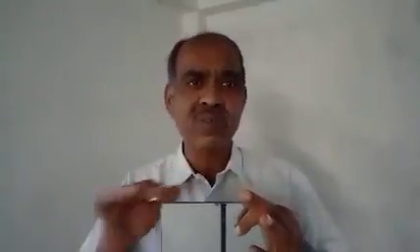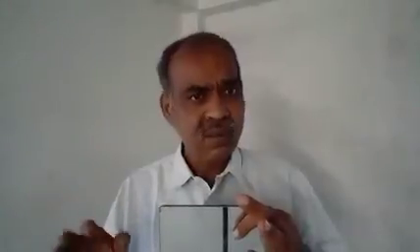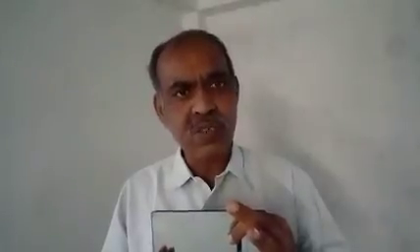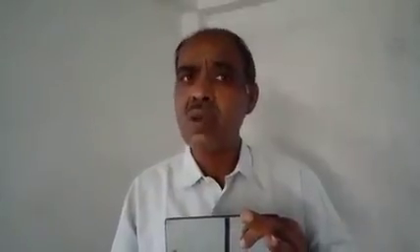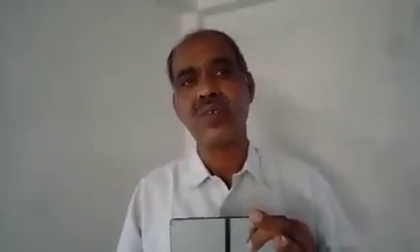The first term vanishes automatically, RA into 0 was there. In the second and third term, L is present. In the right hand side, 0 is there, so divide both sides by L. Then the result is 150G into 2 by 3, which means 100G. So 100G minus 100G plus RB is equal to 0. Minus 100G plus RB is equal to 0. Therefore, RB is equal to 100G.